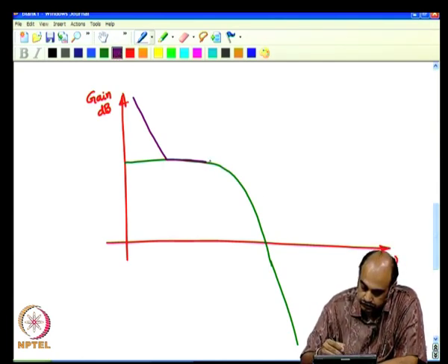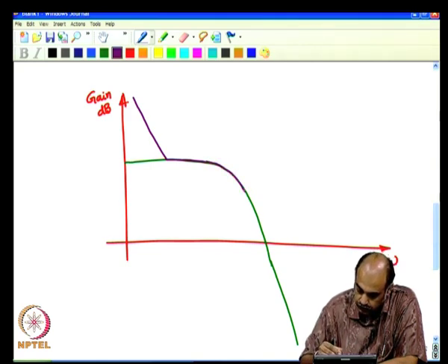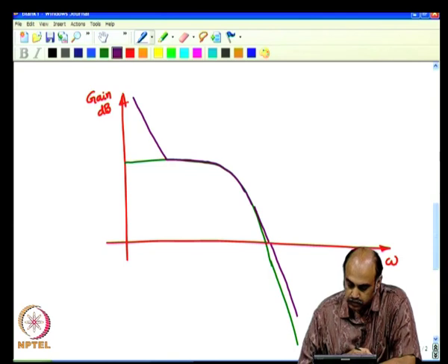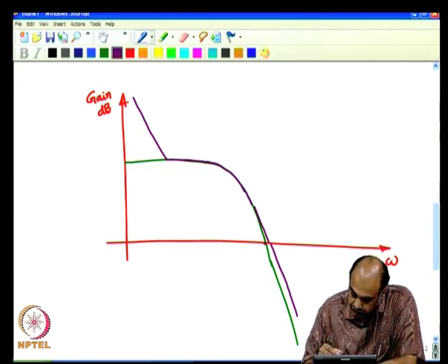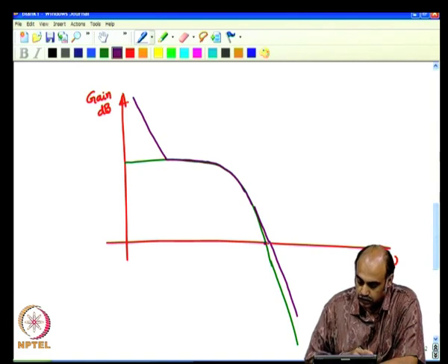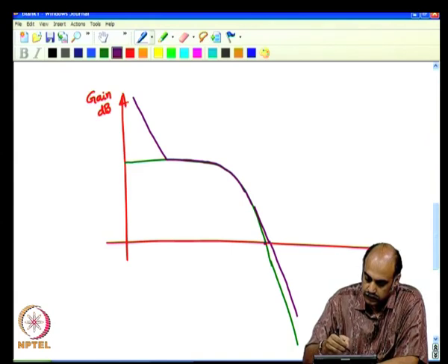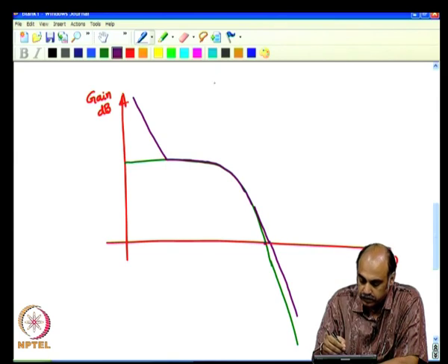Because it is not changing with frequency, and the differential portion is trying to pull up the gain at much higher frequency. So, if it does not make much difference in the bandwidth, if the system is already slower, then it makes good sense not to have the derivative,